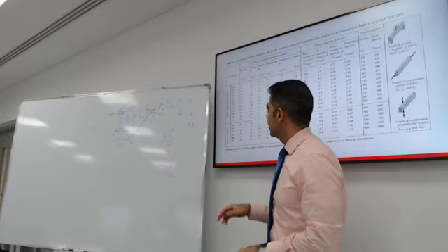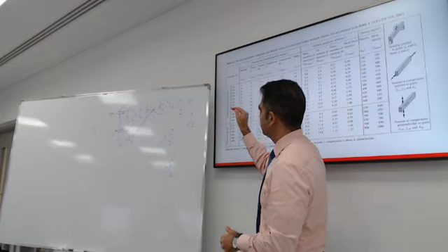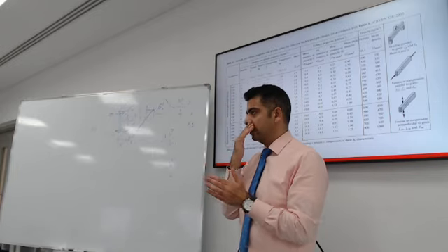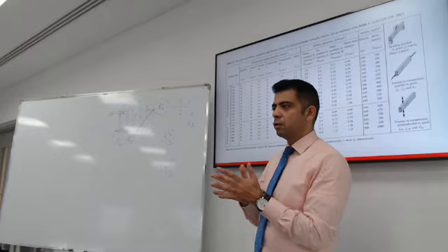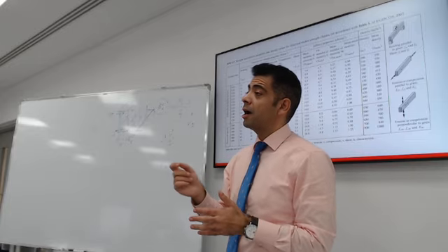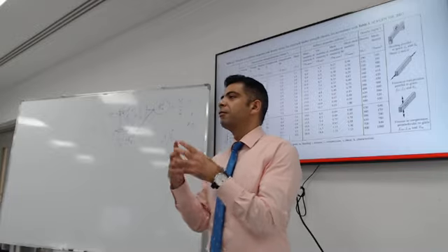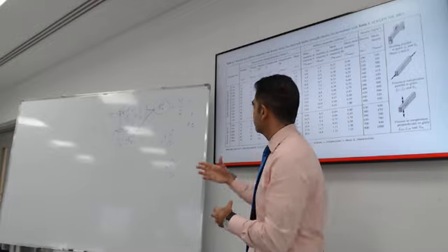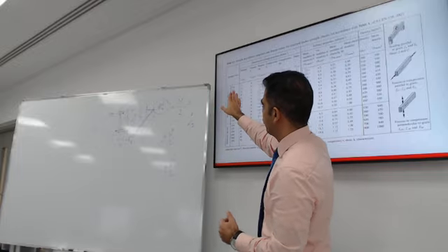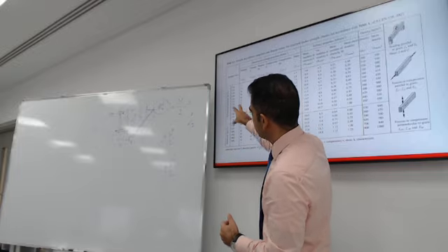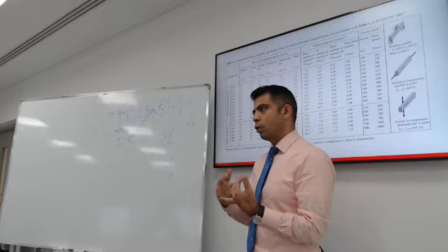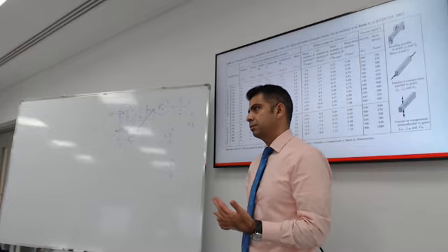All right, that leaves us with the properties of structural timber classes. There are guidelines to give classes for grades of wood. You can think of this as like the steel grades. Do you know what the steel grades are? When you say S275 or S355, it defines what grade of steel it is. So it gives a name for this category of wood. Same thing with C14, C16. As you go higher, the wood gets denser and stronger, more expensive, and less available.